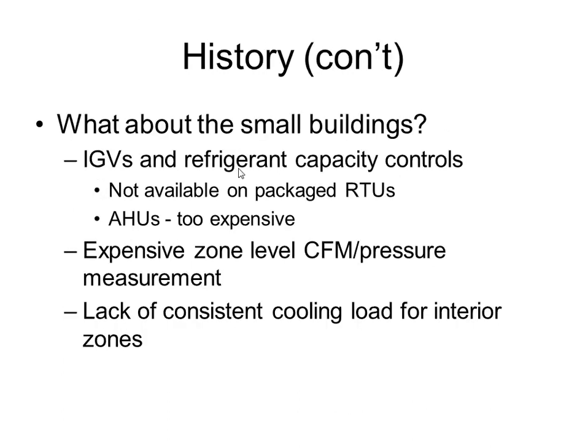Where VVT comes into play is this application for smaller type buildings. Smaller buildings with smaller loads have units that don't have refrigerant capacity control or inlet guide vanes. The more complicated control that's required for VAV applications usually isn't available for smaller tonnage units.